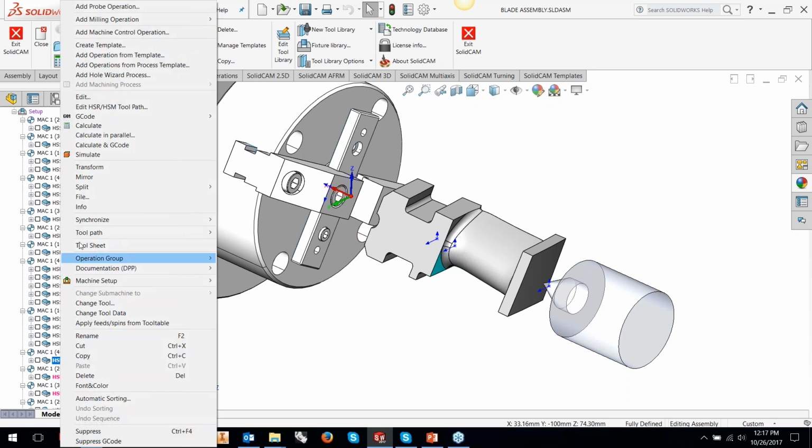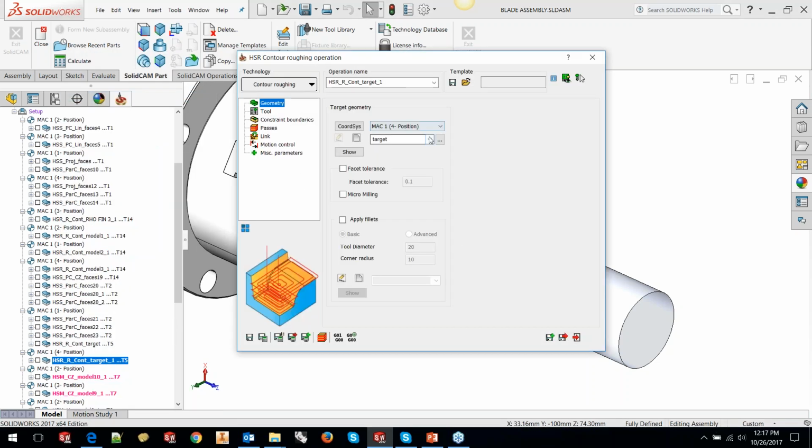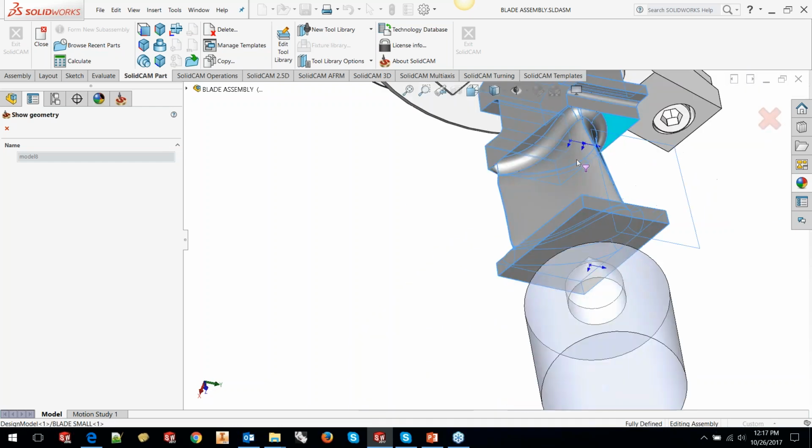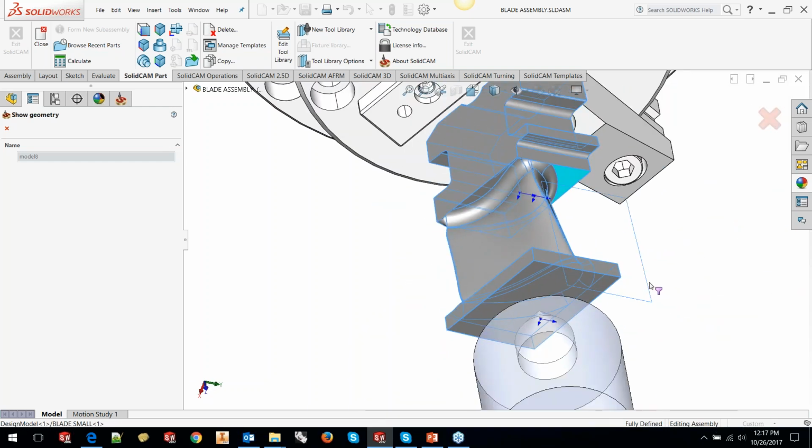And what I have here is, if I edit this toolpath, the original toolpath was with this particular data. Now, what is this particular part? Just to stop the tool from going further down, you can see a surface. We created a surface there so that the toolpath doesn't go below that, because I want the toolpath to go this side and a little bit on the other side. But because there's no control on how much the toolpath has to go deep on either side, once I define the lowest point in Z, it's going to go on either side. So to stop that, we created a surface.